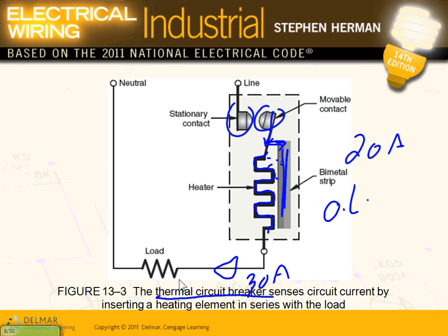Okay. So where does it say on a circuit breaker? If it's thermomagnetic, most of these, we really don't care what the technology is, bimetallic or whatever. What you care about is, if it's a thermal, there's something inside that heats and trips.